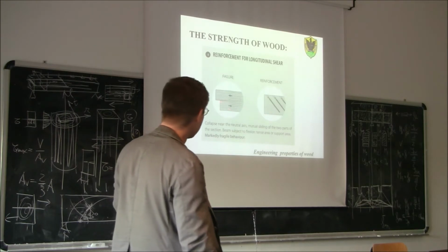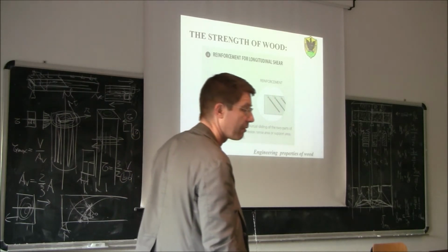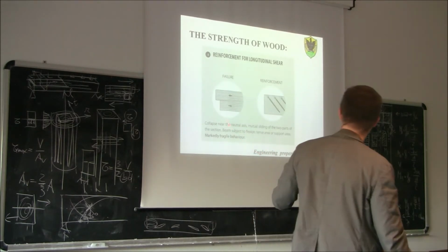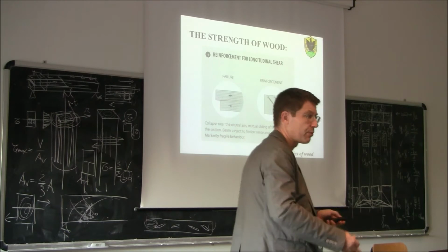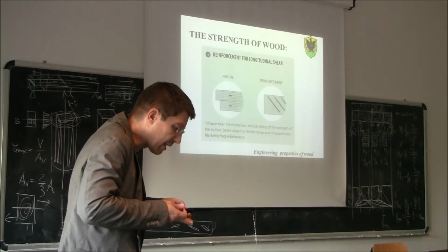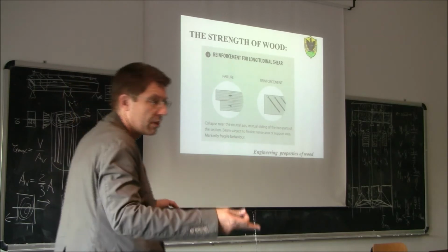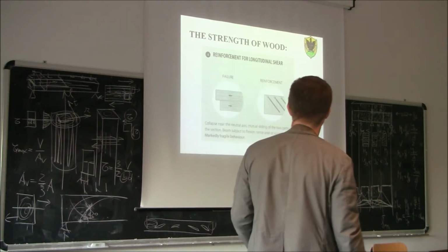And then very often it would be better to reinforce the beam with some screws in order to prevent the propagation of the crack. You may also have a small crack, and if you put the screws, this crack does not propagate anymore. And then you can have the full shear resistance of the beam.